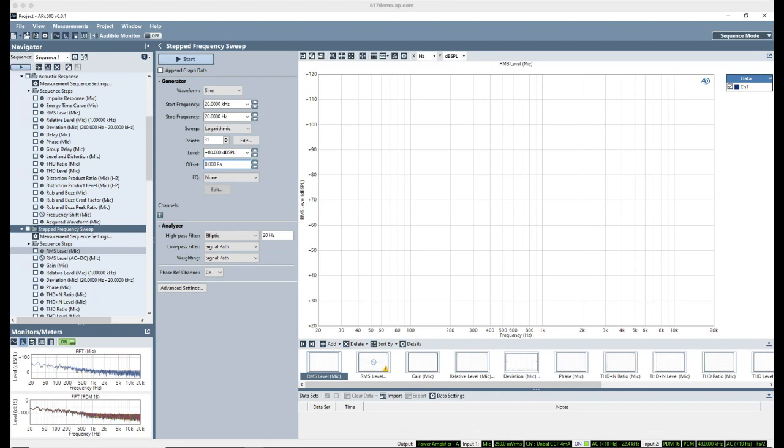Next question is, do MEMS mics need calibration only once, or do they tend to drift significantly in sensitivity over time? So I'll begin my response by saying I'm not a manufacturer of MEMS mics, so this is really just my opinion. My experience with MEMS mics is that their sensitivity is very stable. I've had some MEMS mics that I've used for demonstration purposes for years, maybe as much as 7 or 8 years now, that still have exactly the same sensitivity as when I purchased them.